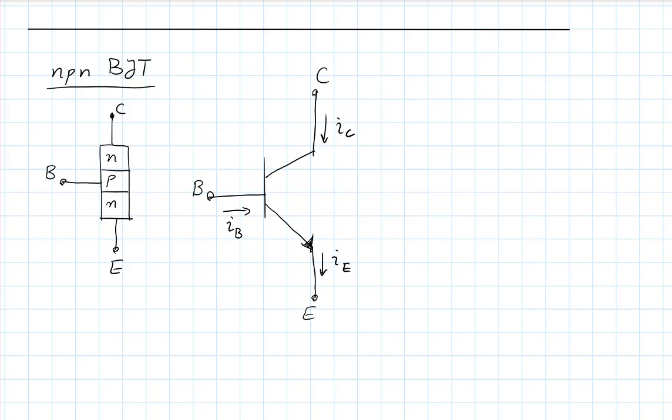And in fact, the 3 currents also are related by KCL, as we said last time. So if you specify 2 of them, the third one would also be known, because IC plus IB going in should equal IE going out. Okay, so you really need to talk about 2 currents and 2 voltages. But most often, it's the behavior of IC, the collector current, as a function of VBE and VCE, which is of interest. And this is what we started to look at last time.